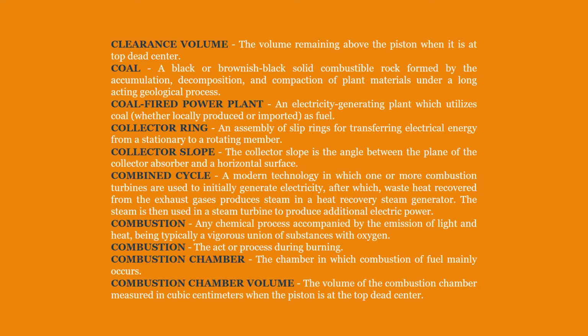Combined cycle. A modern technology in which one or more combustion turbines are used to initially generate electricity, after which waste heat recovered from the exhaust gases produces steam in a heat recovery steam generator. The steam is then used in a steam turbine to produce additional electric power.